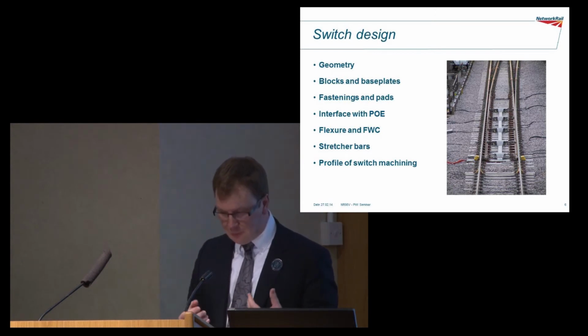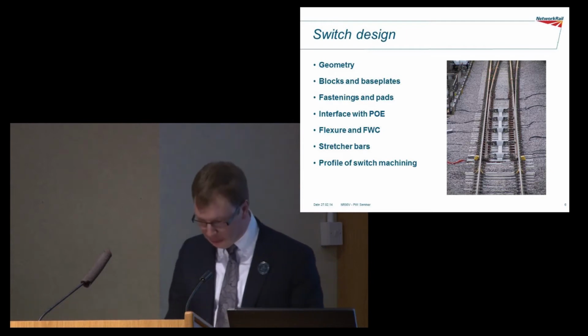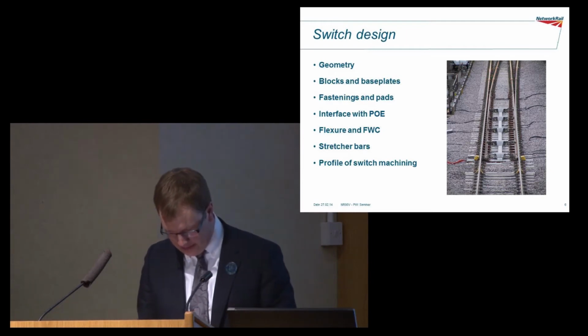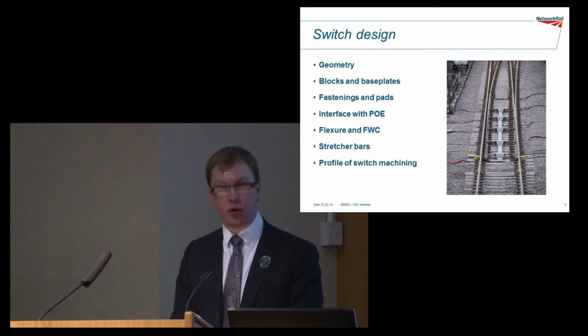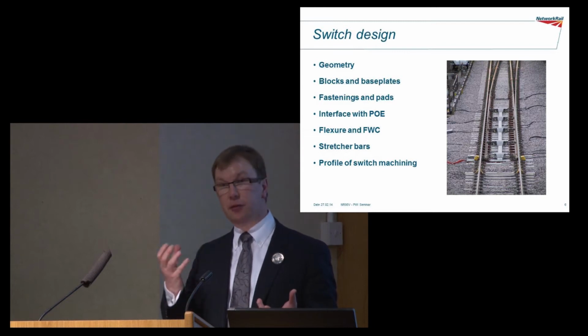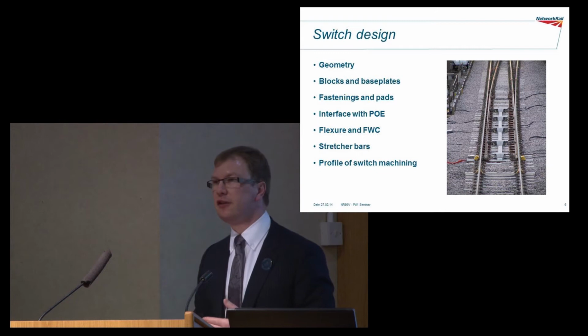Within the switch, just like within the rest of the layout, it's which clips are we going to use, what toe load do we need to apply. Then we get to the POE, points operating equipment, the supplementary drive as well as the primary drive, all the compatibility issues. We need to think of S&C as a system.